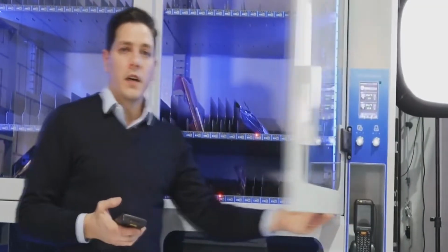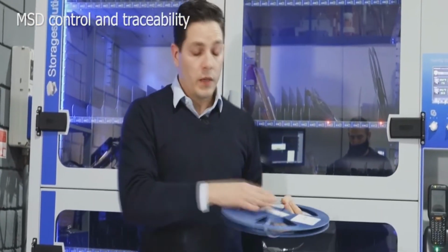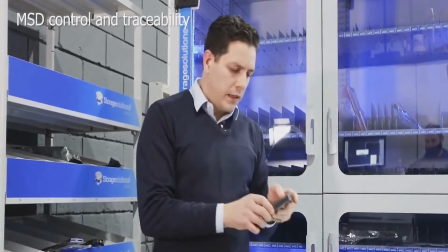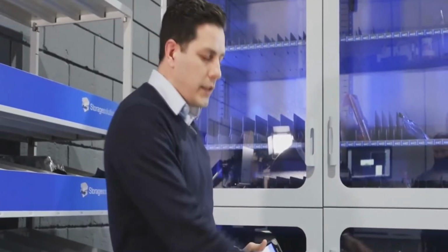All our equipment are equipped with humidity control. So if this was an MSD component, when it comes out, I start counting the floor life. The PDA also allows us to keep track of MSD with the components inside a bag. I can tell the software that I'm going to set out of the bag this component here. I will scan the unique ID and set the reel out. And now the reel is out of the bag. Actually, it is a JEDEC tray. The JEDEC tray is out of the bag.